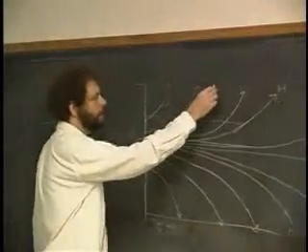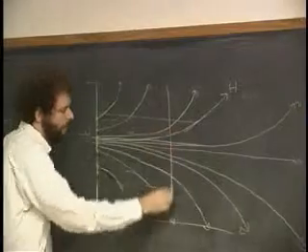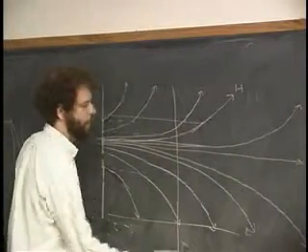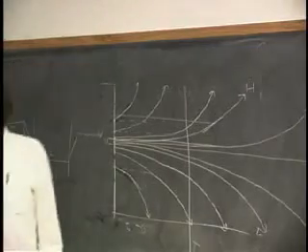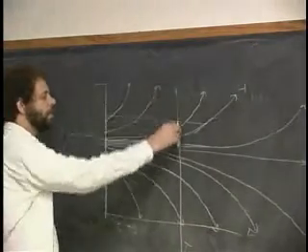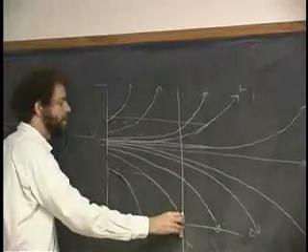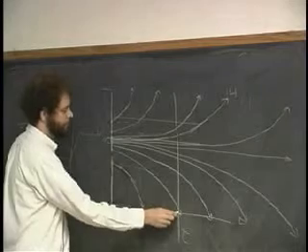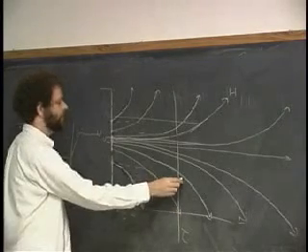Let's say that I decide that I want all metastability to be over by time t here. In other words, I want all of the metastability to be done by this time. Well, that's true for this curve. It's true for this curve. It's not true for that curve.